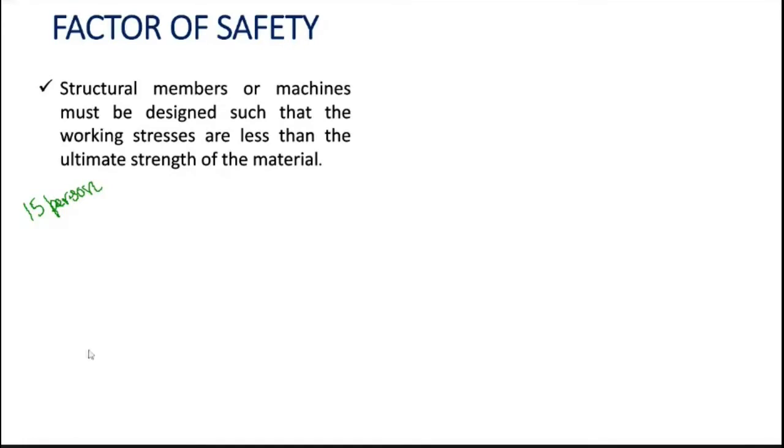But in our case, we will be going 25. So the lift carries more than this. Even with 25, the lift will move and work properly. But it is mentioned in the lift that it is applicable only for 15. This is what we call the factor of safety.